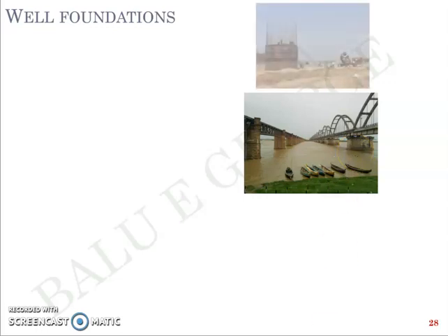Now, well foundation, as the name suggests, has got its resemblance with a well. It's big, it's circular, and it's deep. So the well foundation is a huge structure by its scale compared to the usual structures that we see around as foundations, and it is used to have a greater load transmission, which means it's transferring the load to a greater area, and of course it can transfer a heavy load as well. So that's why we used to choose this well foundation for bridge structures.